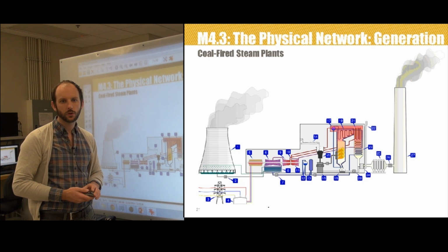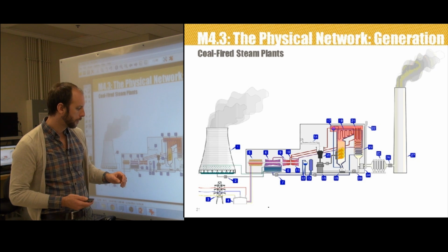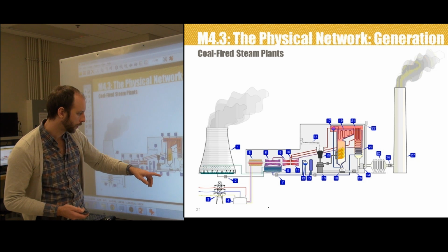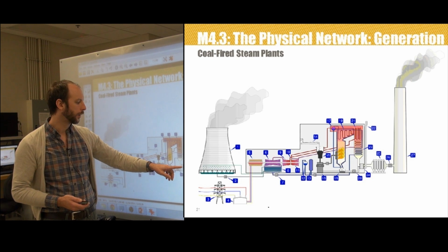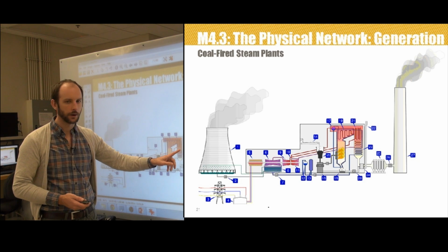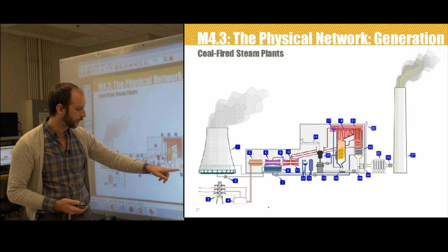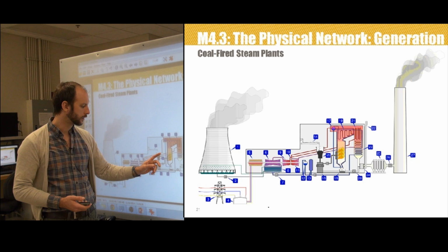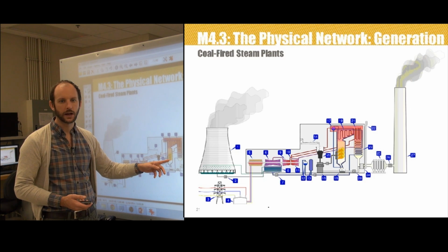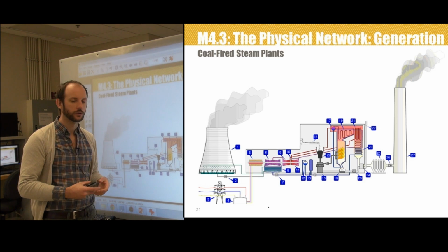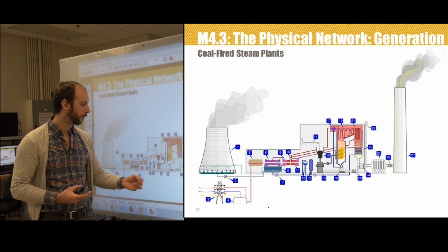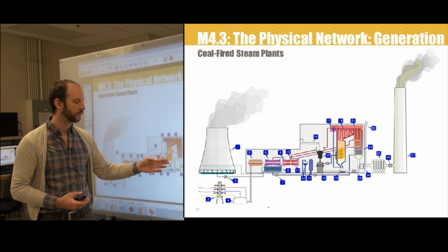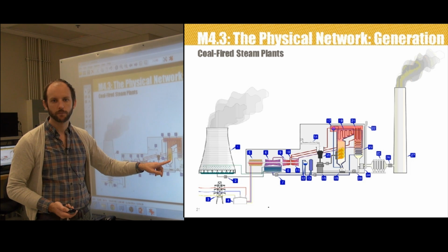The coal dust is then mixed with preheated air. The preheated air here is shown as number 24. There's air coming in. It's already gone past this hot boiler system, so it's warmed up air. It's being pushed by this fan, which is often called the draft fan. And so down here, the coal dust and warm air are combining. And this hot, what is called an air-fuel mixture, is then forced at high pressure and high velocities into this boiler, where it will meet the flame and rapidly ignite inside the boiler system.